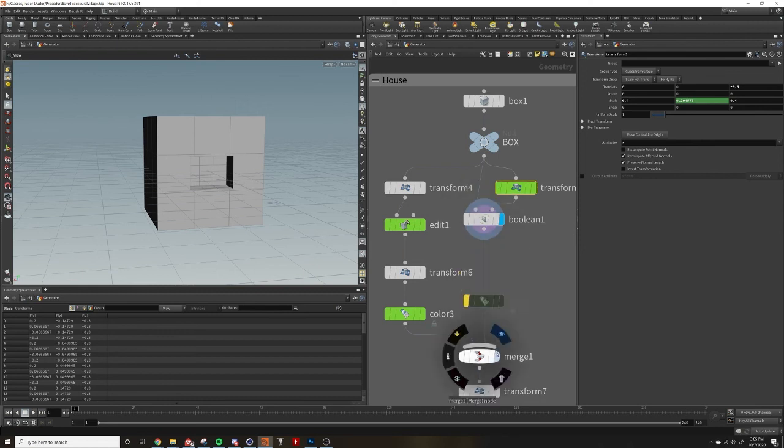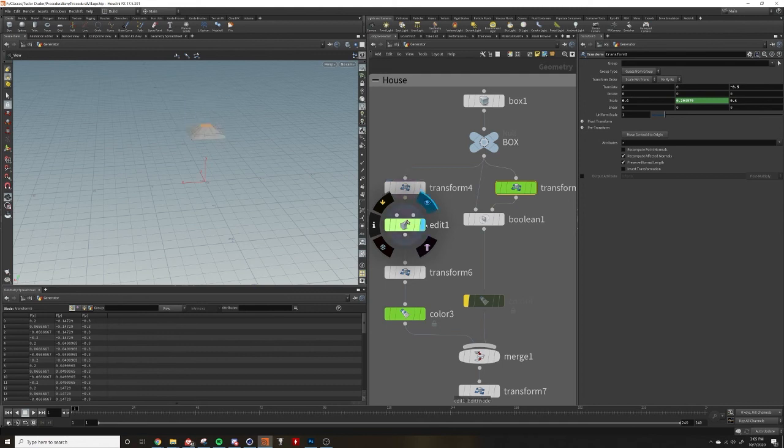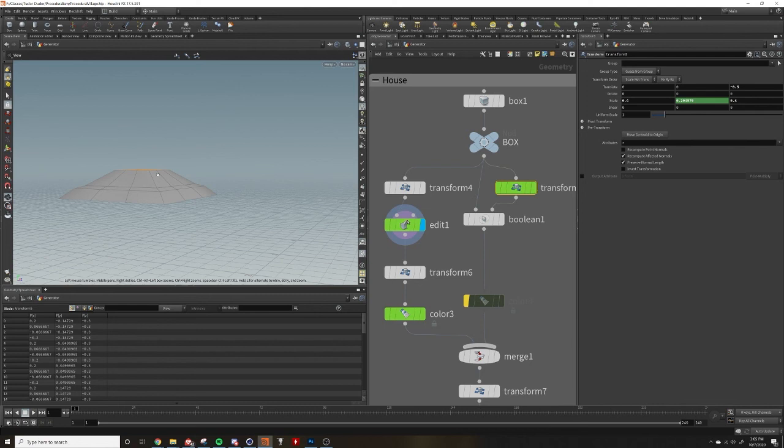And over here, I moved this square up from where it was, and then I edited the geometry a little bit to be this house, or this roof shape. And then I selected this area and I added that random amount, and it's going to pick a number between, let's say, 0 and 2, and it's going to pull between those, and it's going to give me some random roof heights for my buildings so that I can get a more dynamic look for my scene.